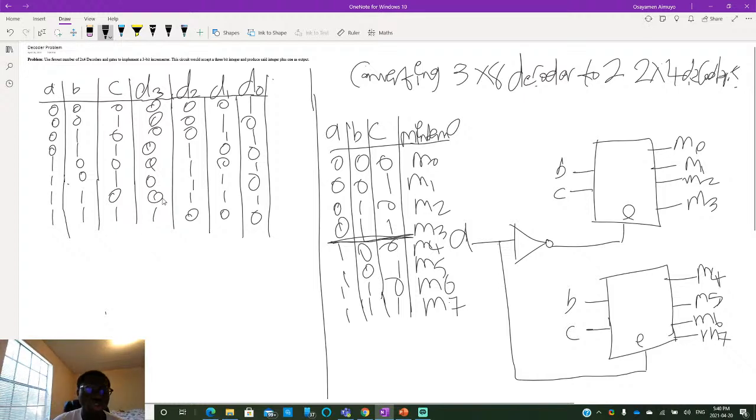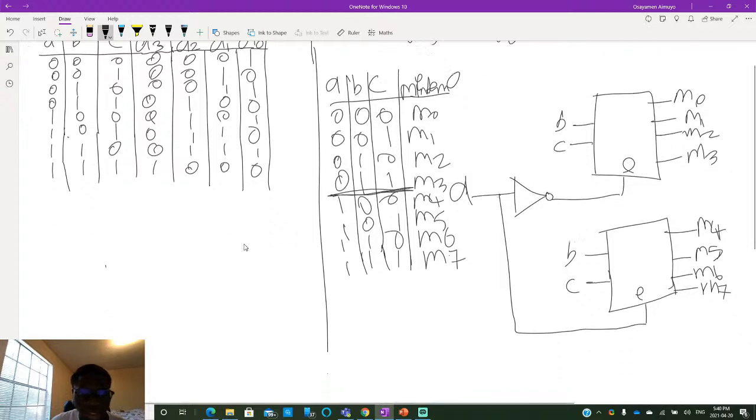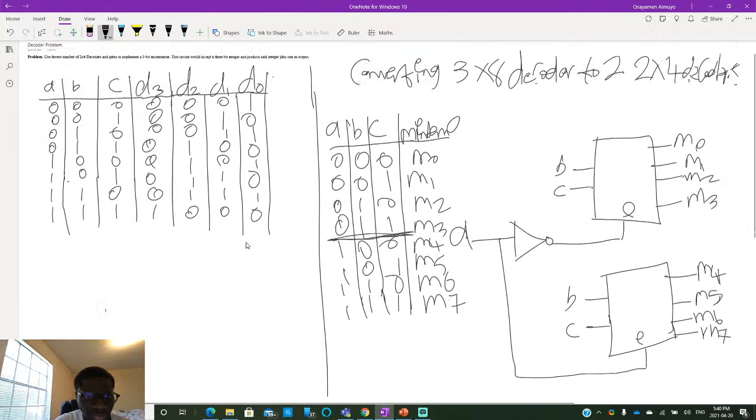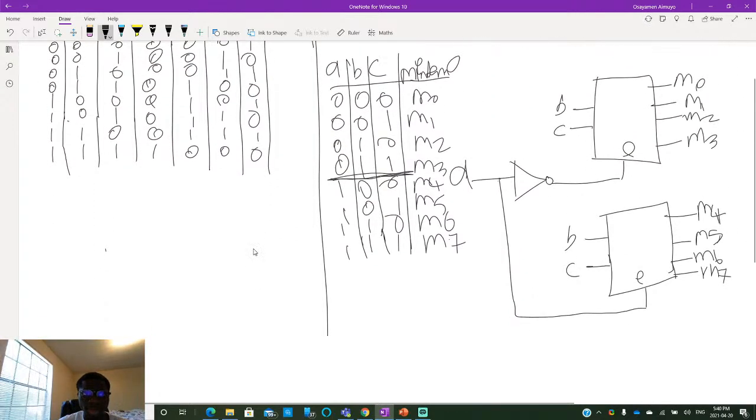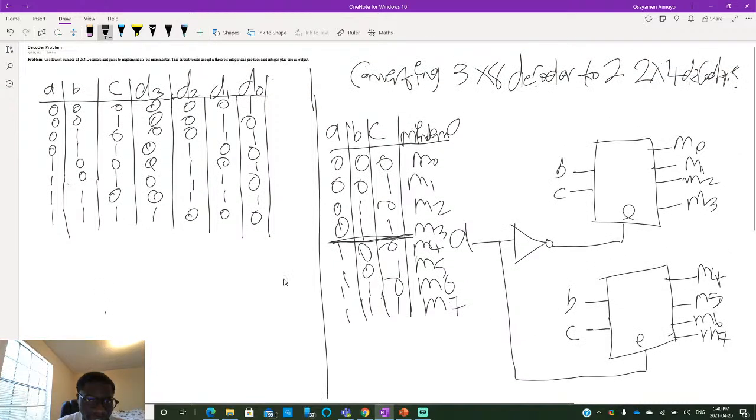We have the truth table for the incrementer. All that we have to do now is to get the circuits. But first of all, notice that for D3, the only one we have is for this minterm. And for D2, we have ones for these four minterms, correct?